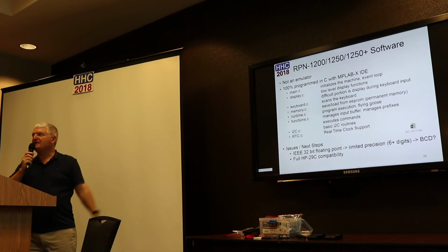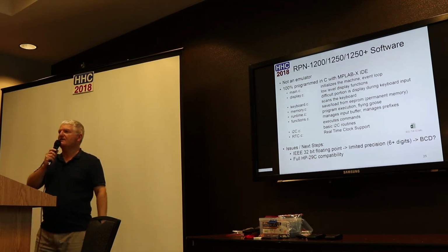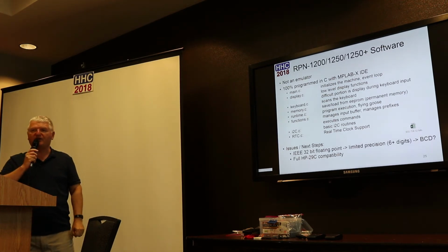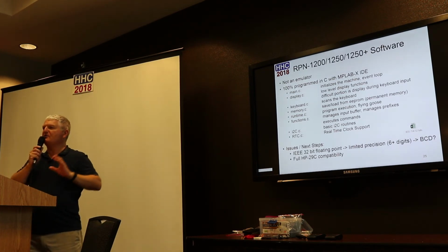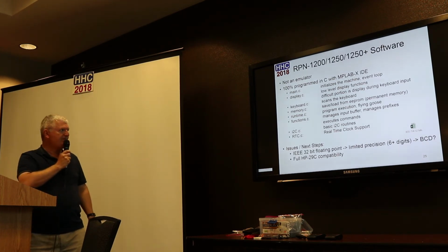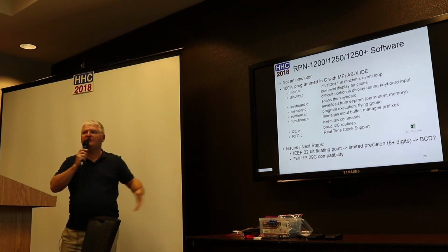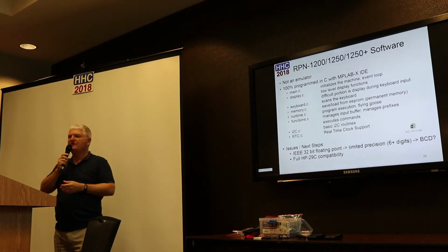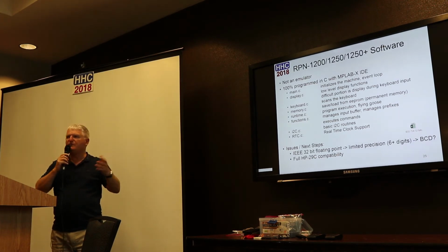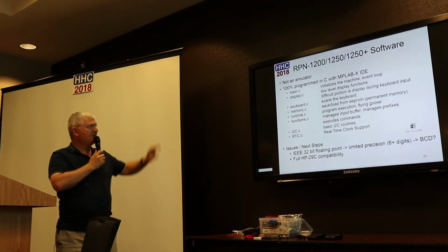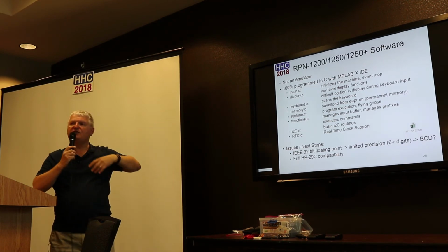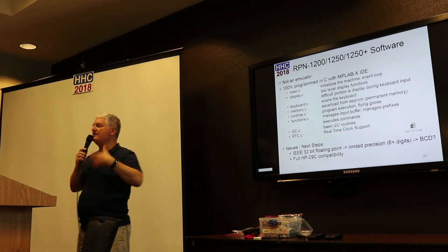Everything is programmed in C using the MPLAB X IDE from Microchip, and I use the free version, so it's not an optimized compiler and so on, but it works very well. There are a few files here, and if any of you is interested, I can share that on the hpmuseum.org or whatever means works. Main.c is essentially initializing the machine and runs the event loop.